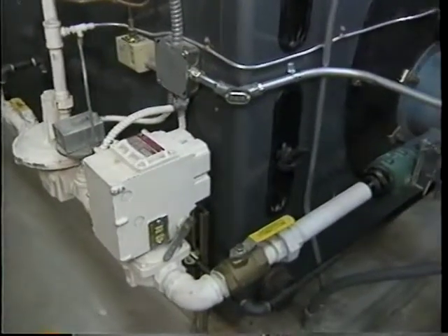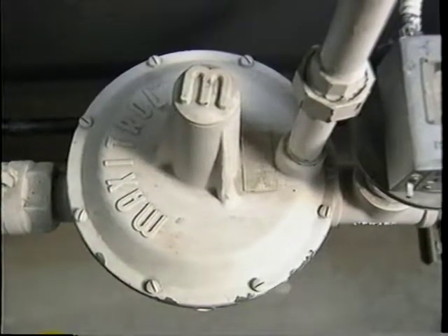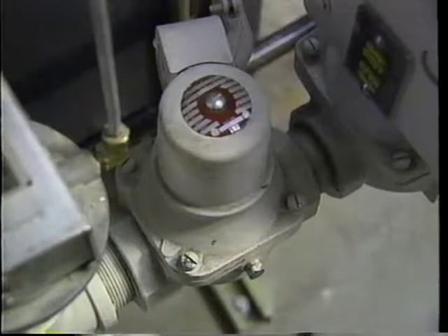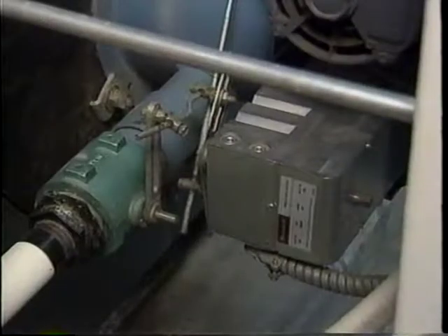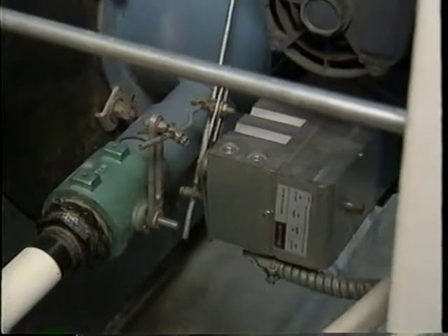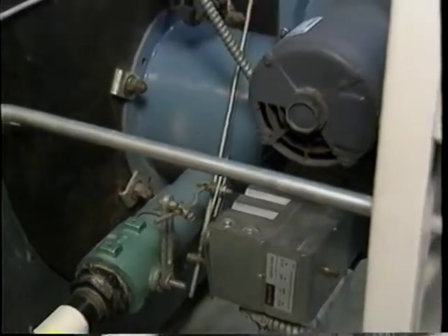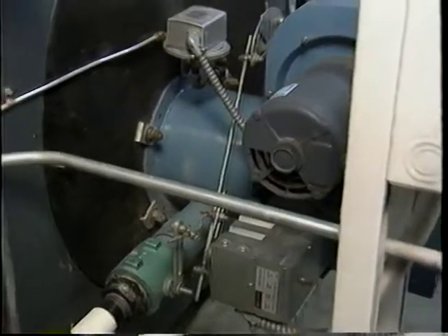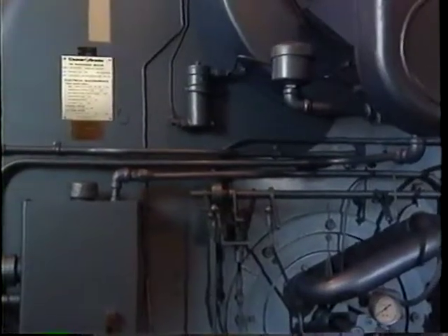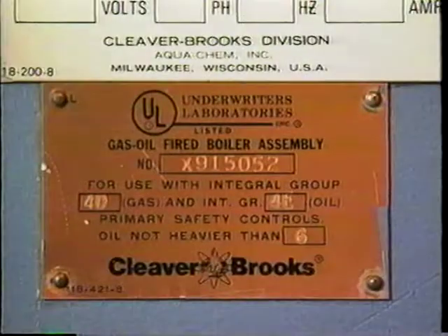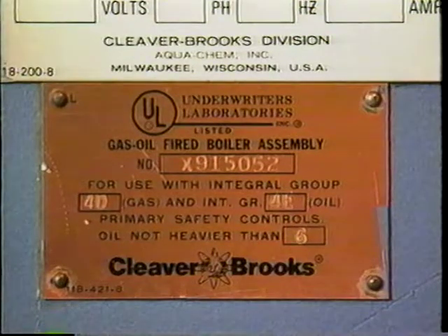In a high-pressure gas system, gas passes through the regulator and pressure is reduced to the proper pressure for the burner. A solenoid valve opens at the right time in the cycle to admit gas to the butterfly valve. The butterfly valve controls the firing rate through the gas linkage. Some boilers have combination burners, which can burn gas, fuel oil, or a combination of both gas and fuel oil.